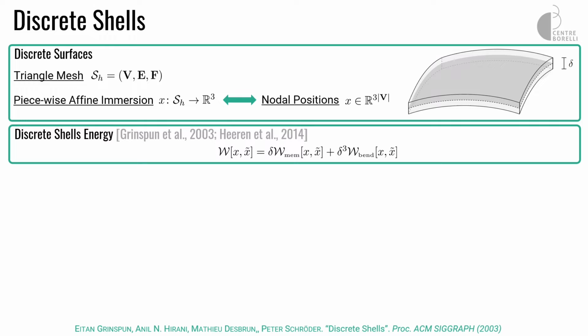And something similar applies if you think about, for example, a piece of aluminum in your kitchen. It's very easy to bend, very easy to crumble. But it's relatively stiff to membrane deformations, because it will tear basically. So it won't deform elastically anymore, it will just tear. But if you have a thicker sheet of aluminum, you can actually distort it in plane, but it's much harder to bend. That's sort of why we expect this regime, not delta but delta to the power of 2,